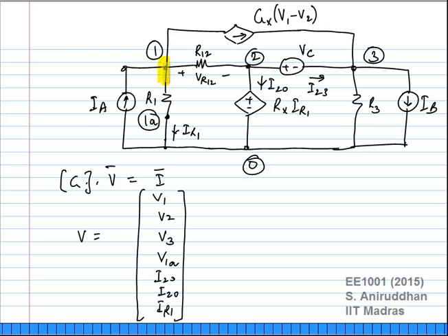Now we know that the source vector consists of only current source values and voltage source values, for example. Depending on which element you are representing, corresponding to that row, you will have that particular element. If you have an independent current source connected to a particular node, that will contribute to the right hand side. If you have a voltage source between two nodes which is giving you a voltage constraint, that could be put in the other node and so on the right hand side.